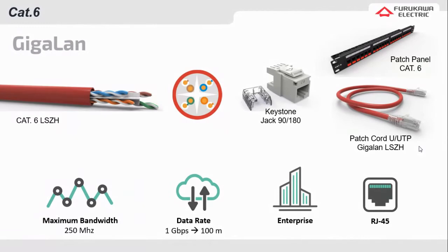On the other, it contains no halogens, and so the toxicity of the gas is quite low. Keep in mind that smoke and fumes can be more of a hazard than flames themselves in the early stages of a fire. So LSZH cables are safer for both people and the environment, and that's why many industries have seen an increasing demand for them.